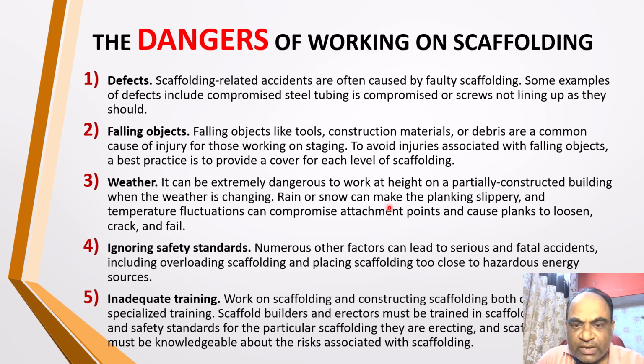Rain or snow can make the planking slippery, and temperature fluctuations can compromise attachment points and cause planks to loosen, crack and fail. That could be a dangerous situation. So if bad weather is there, the scaffolding must be evacuated as early as possible. The workers should not take any risk.